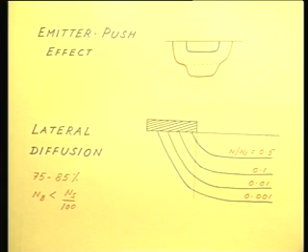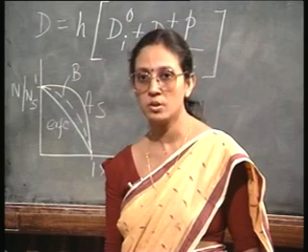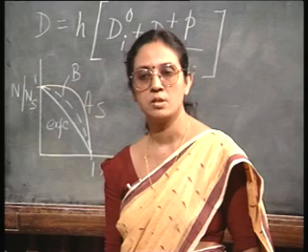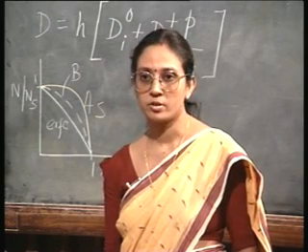If you do not want to have this emitter push effect, do not use phosphorus, use arsenic. Arsenic will not give rise to this emitter push effect.